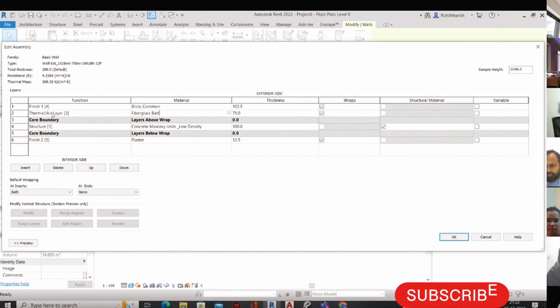Now with different functions and materials, we have to define thickness as well. In this thickness column, you have specified thickness, for example for finish. The finish is of brick, and the thickness of that finish layer is 102.5 mm. Then you have the thermal air layer, that is your fiberglass batt, it is 75 mm. Then you have structure. This is the main component which will give strength. It is 100 mm. And then the inner finish is 12.5 mm, that is of plaster.